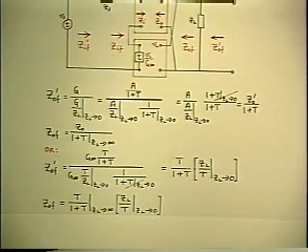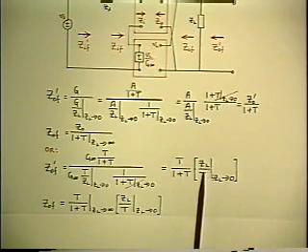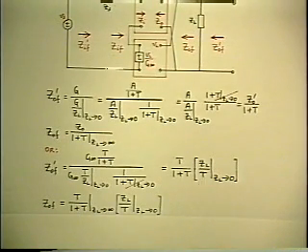See, it doesn't matter what the open loop output impedances were, which is why you didn't bother knowing them. The loop gain alone determines the output impedance of your closed loop system. Which stacks up even more to the argument that the loop gain is the central important quantity. Because it's going to determine not only the closed loop gain, it's also going to determine the output impedances.